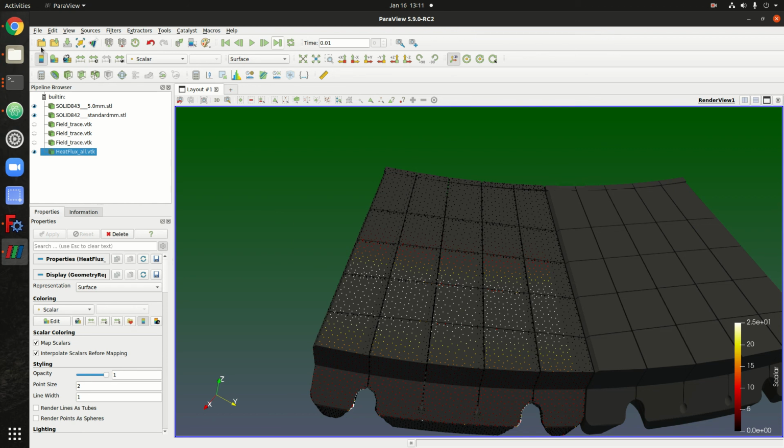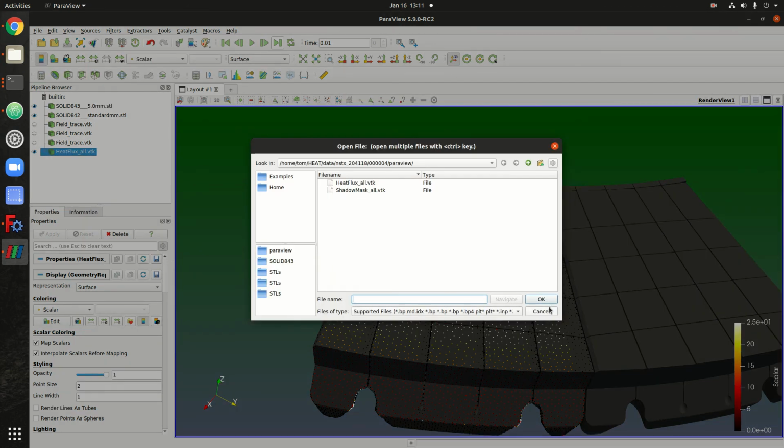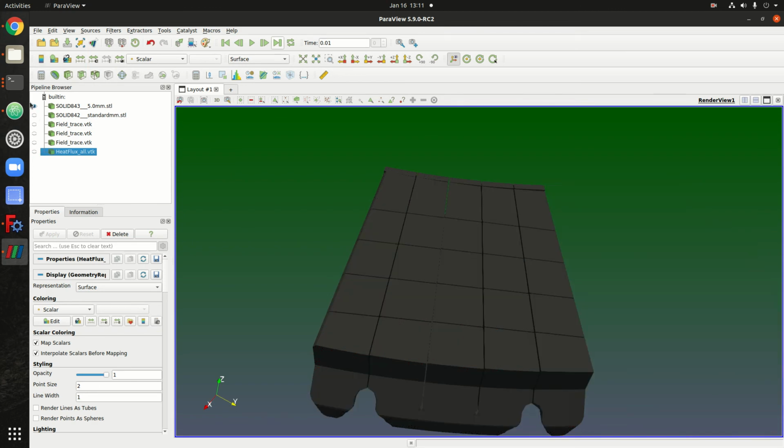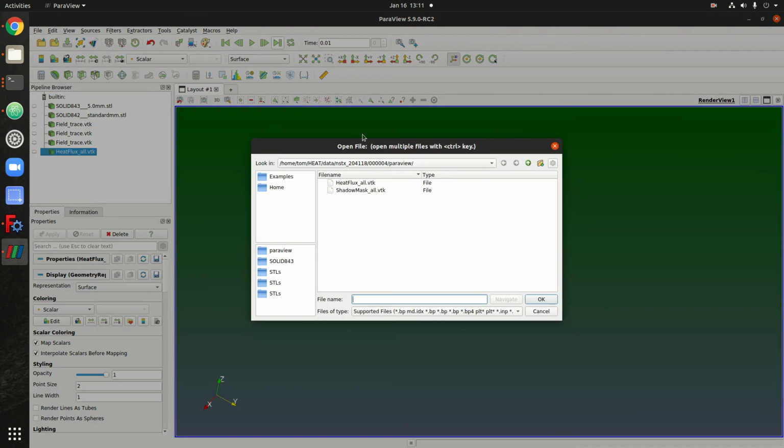If we want to then see the temperature, actually before I open anything, I'm going to turn all these tiles off, and then I'm going to come back out to my shot. So this is my data directory and then the machine under dash shot number, and I'm going to go to OpenFOAM. I'm going to go to heat foam. This is the tile that we calculated the temperature on, and I'm going to open solid843.foam.